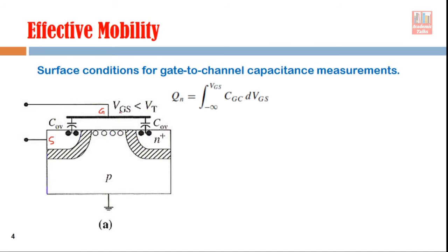Now, if the gate source voltage is less than Vt, or you can say when a negative voltage is applied here, this VGS is a negative value. What will happen in that case? The free holes which are present in the semiconductor will be attracted. In the drain and source region there are N-type carriers, and in the channel there are P-type carriers. So there is a type of P-N isolation, right? And this electrode is not connected to the channel region.